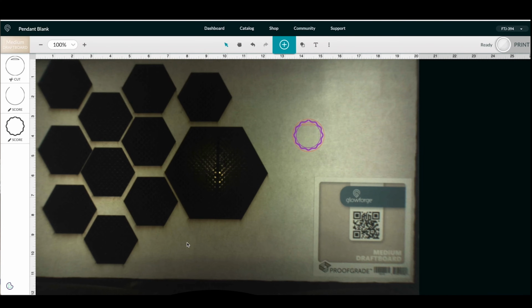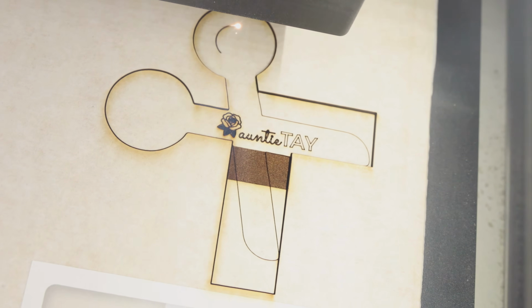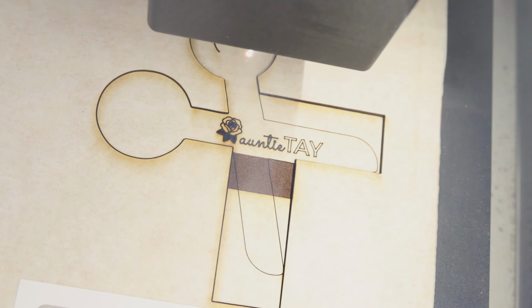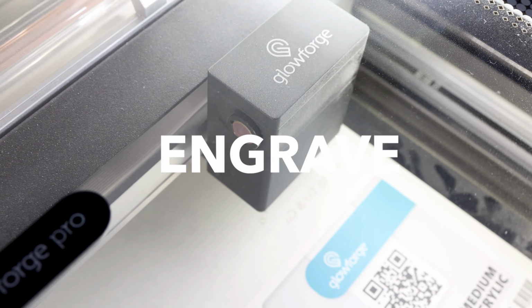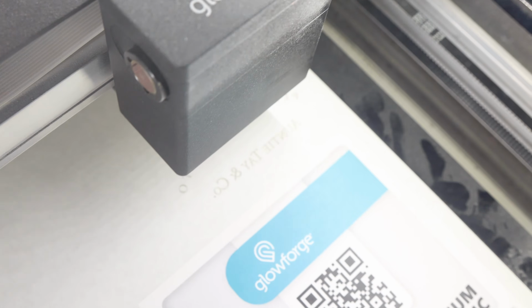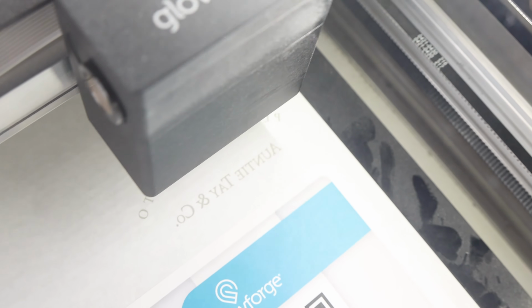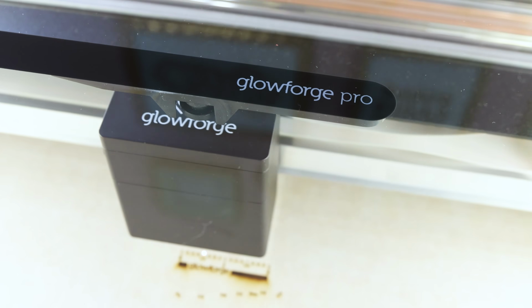So, what are these functions, and in what order do you want to accomplish them? Cut. This is the most obvious. You'll likely use the full power of the laser at a low speed to cut through your material. Engrave. The laser will move back and forth at a much lower power and a quicker speed to remove part of the surface of your material, leaving a divot or an engraving.